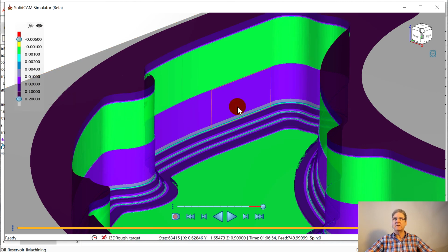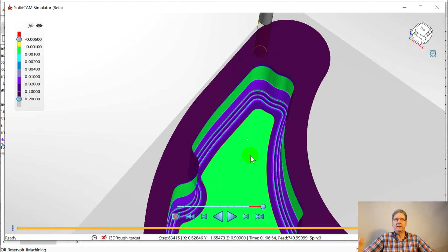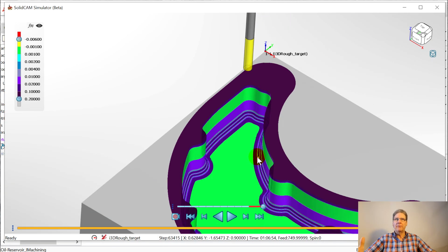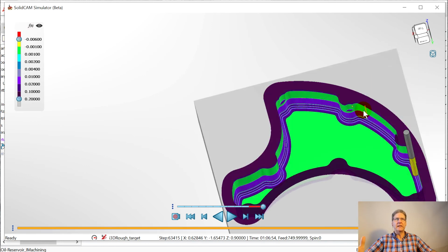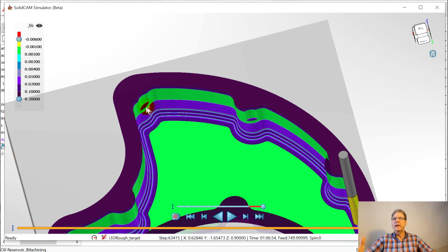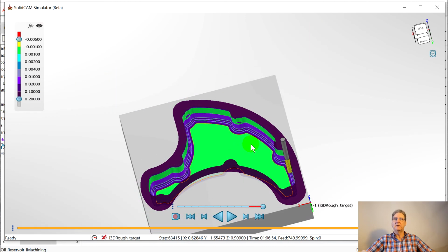That's over 10 thousandths step, halfway down, for reasons I can't understand. It got the floor of the part correct. Then similarly, you think, oh, floors it gets, no, the floor here and the floor here, it left at least, what, 10 to 20 thousandths, according to the color codes.